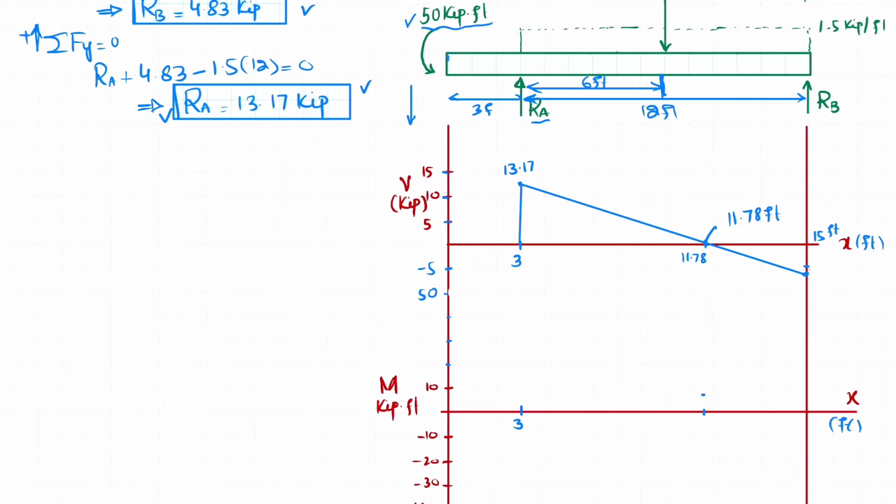Again you can see the shear is first degree and the slope is decreasing, so the bending moment will be second degree and it will be clockwise. So we will join them. It should be in curve form. So this point is 7.78 kips into feet.